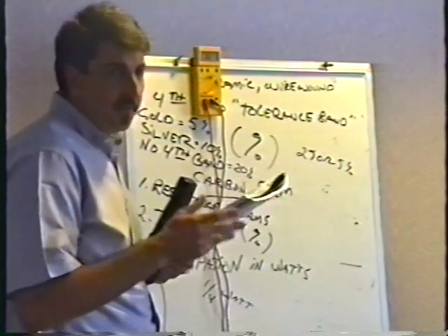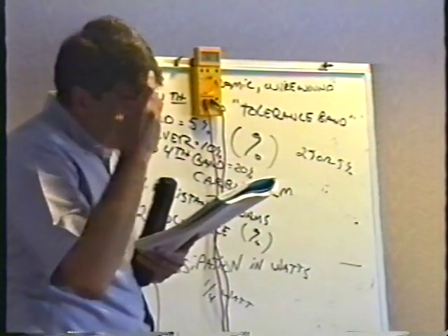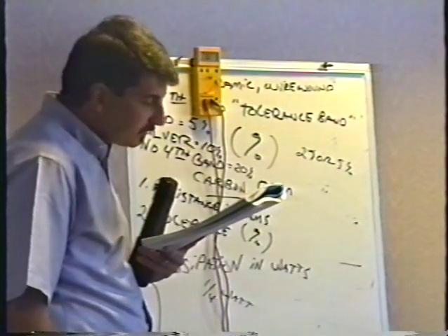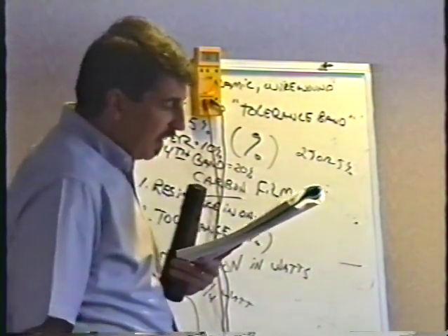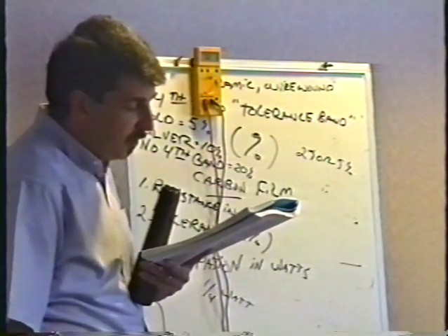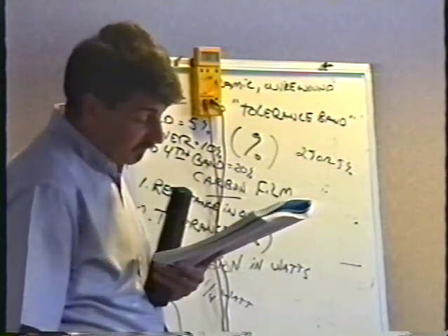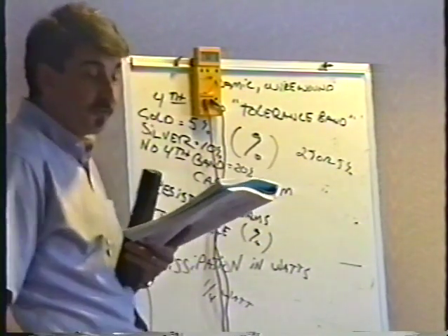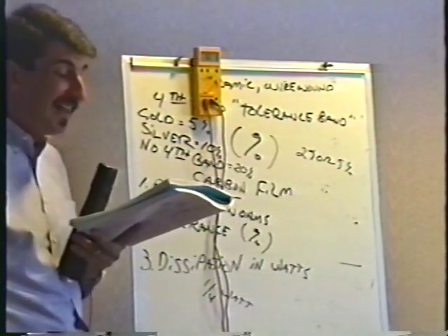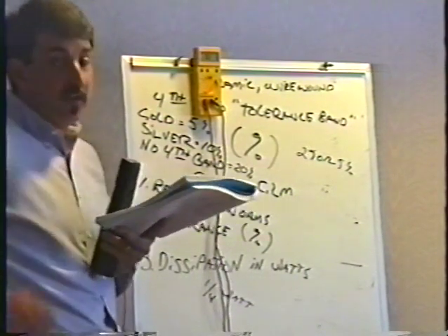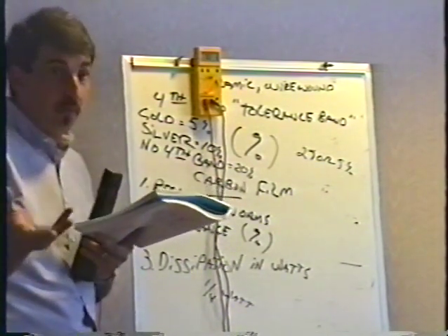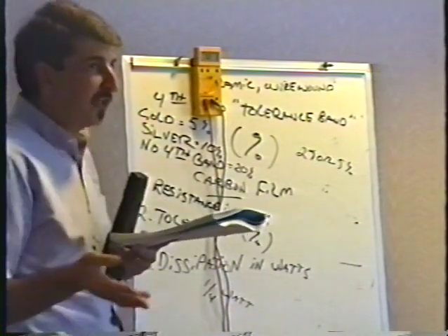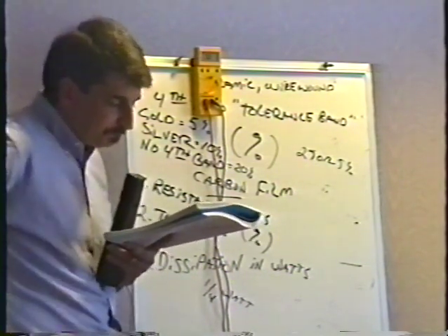Number 8, stop me if you have any questions, by the way. Number 8, red, red, yellow, 220K, 5%. Number 9, white, brown, brown, 910 ohms, 10%. The silver's 10%. Number 10, yellow, violet, gold, gold. That's one of those fractional multipliers. Yellow, violet is 47. The gold says times 0.1, 4.7 ohms, 5%. I think you'll find that all your fractional multipliers will be 5%.